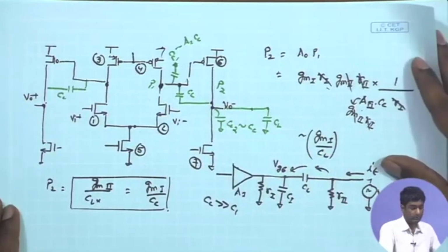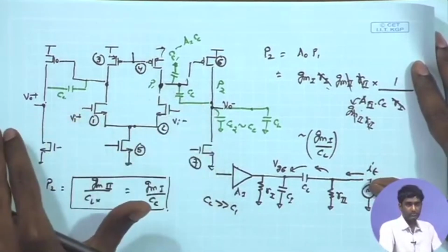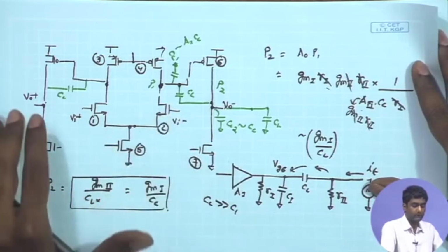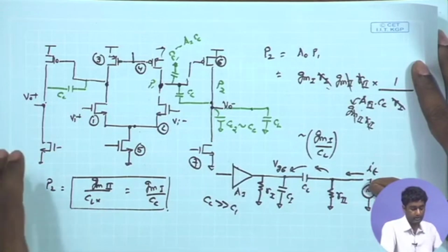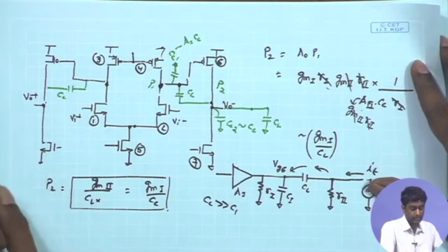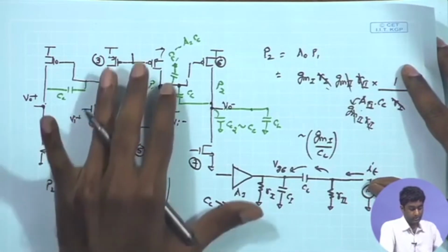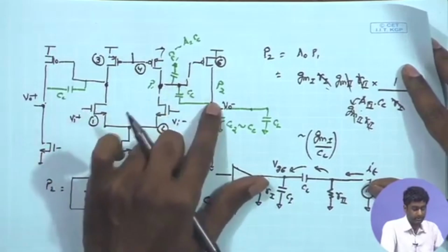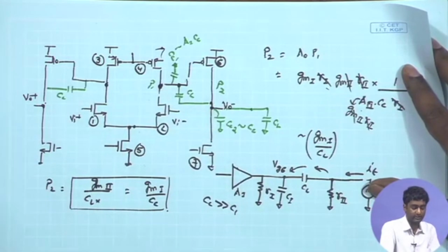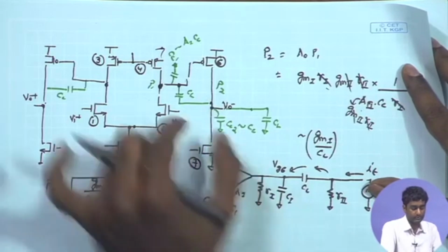Okay, so we can go towards the other issue which comes up with this CC, and that is the case of zeros. We have ignored throughout the zeros coming up in the differential amplifier or the operational amplifier circuits, and they can also play a very crucial role in determining the overall stability. They can affect your stability in a negative manner. So, let us look at the concept of zero. How does it arise in this circuit, what is its effect on the overall phase response, and how to resolve that effect using some appropriate components added in the feedback loop.